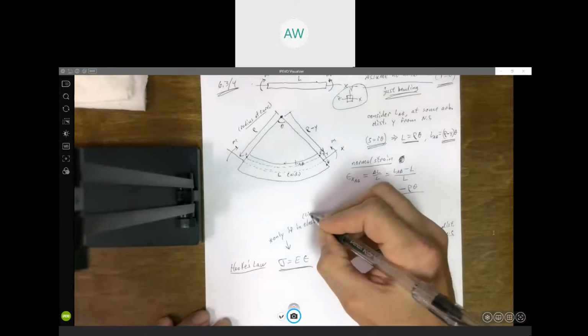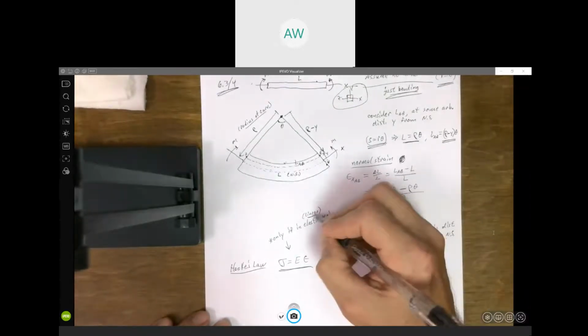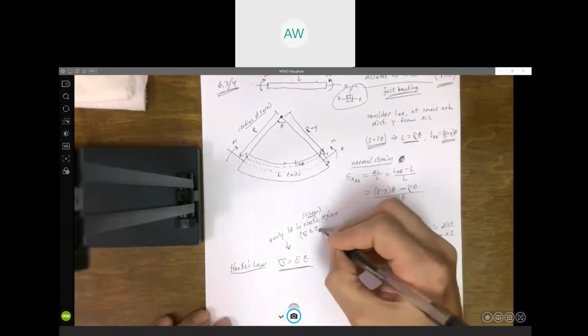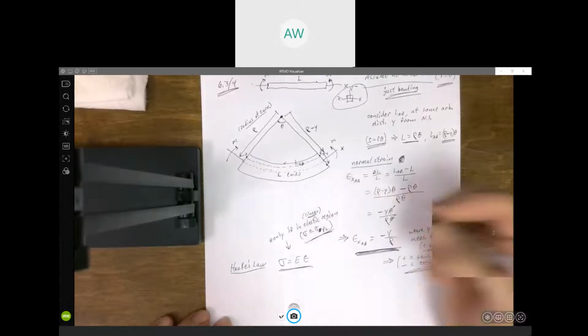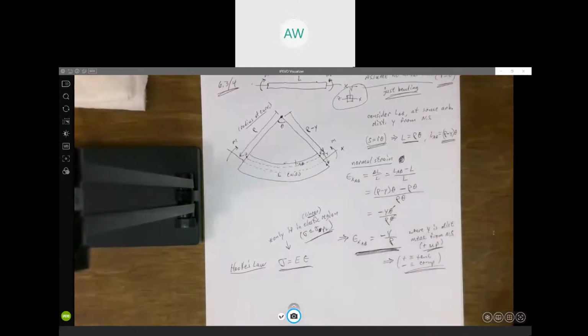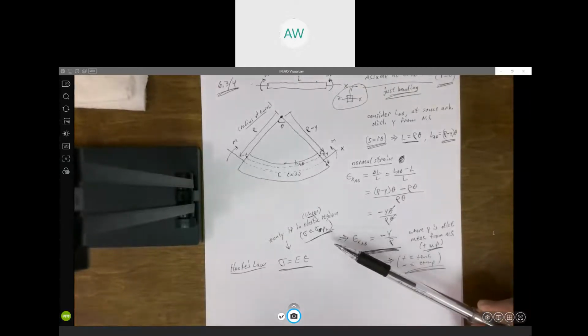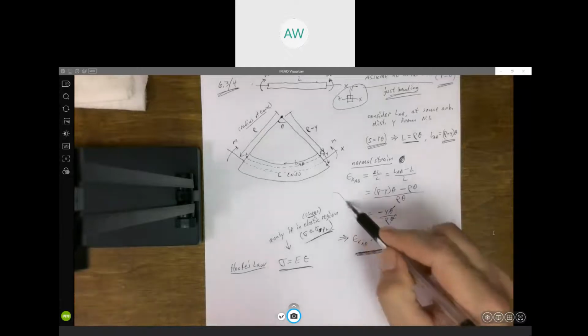Again, elastic here, if you're looking at the stress strain diagram, the linear part, this is where stress is proportional, we'll use proportional limit. As I've said a few times already, you're going to find a lot of our formulas we use in stress analysis are based on Hooke's law, which do have some limitations in that it's only valid for stresses less than that proportional limit. But as I've said before, in the real world, that's where your stresses will be.